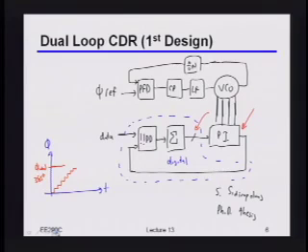What you essentially say is, let me use some sort of phase lock loop that uses a quote-unquote good reference clock just to generate the right frequency to begin with, or something that's at least close to the right frequency. Okay? If I do that and I really do have a clean reference, then I can make the loop bandwidth for this PLL whatever it needs to be, based upon the noise I have on that reference versus the noise I would have had in this VCO. And again, that would tend to be something fairly high if you actually had a clean reference available.